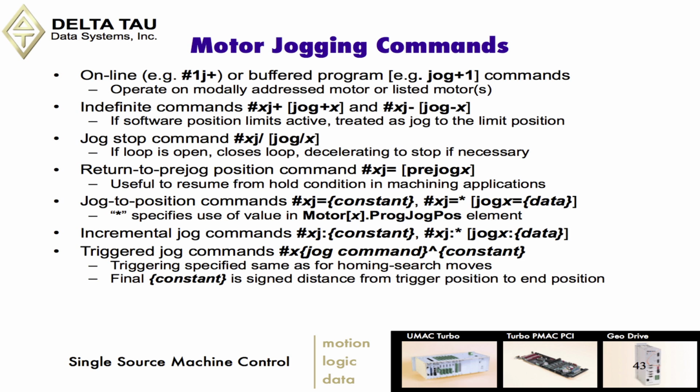In other words, we could say jog +1, 2, 3. And these are indefinite commands. So if software position limits are active, it would jog into the position limit and stop.